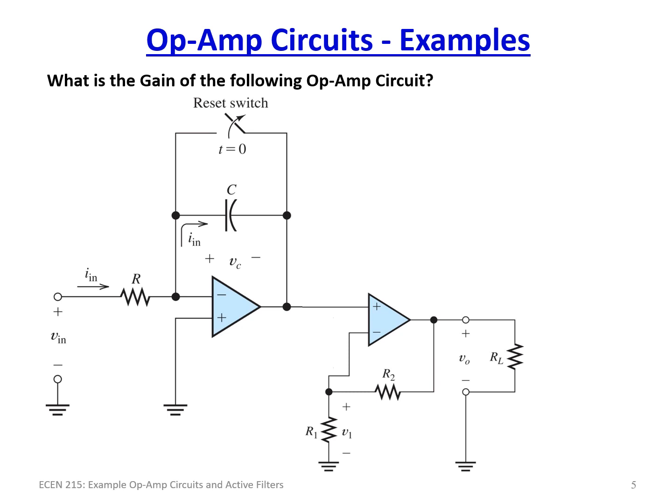Again, this one here is just simply minus 1 over RC, the integral from 0 to t, t being time, of Vin of t dt. So that's this stage. This is the output of this particular amplifier.